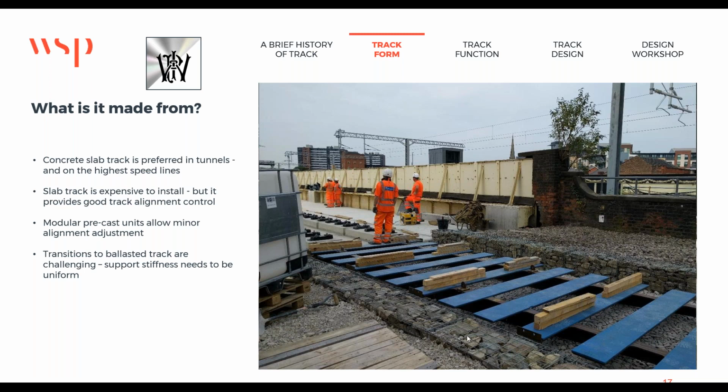So that was always a common run-on, run-off problem in structures, wasn't it? With the lateral flow of ballast, you would lose top because the ballast was wanting to migrate outwards, and that seems a pretty good potential solution for that. Yeah, I like that. That's right. And the idea was that stiffness would be increased by the different width of unconsolidated ballast, where it's held, and the gabion basket idea.